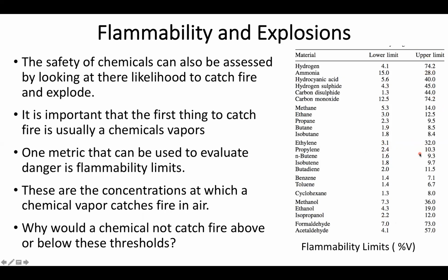But it's worth noting that a fire requires two parts: fuel and oxygen. And if I have too much fuel in the atmosphere, this means I don't have any oxygen and the fire will quickly smother itself out. So what you have to really watch out for is going to be cases where I have some intermediate amount of fuel present in the atmosphere.